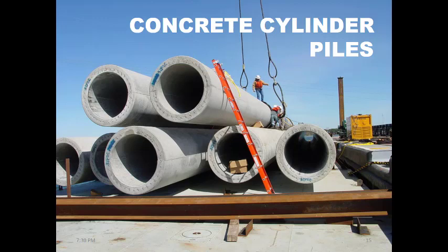Well, there are other perspectives where you have to be really careful, like how you will be loading the pile for positioning it, because as you see from the cables and from the hooks, you cannot just simply hang the pile from wherever you find it necessary and move it.